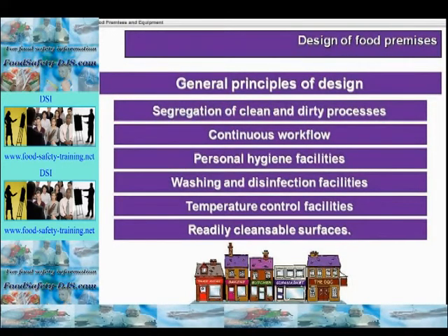Under Regulation EC 852/2004, the layout, design, construction and size of food premises shall, first of all, permit adequate cleaning and/or disinfection, minimise airborne contamination and provide adequate space. Secondly, prevent accumulations of dirt, condensation or mould growth. Materials must be non-toxic and non-flaking. Third, permit good hygiene practices and prevent cross-contamination, especially from pests. And fourth, provide suitable temperature conditions for food handling and storage, including monitoring and recording.